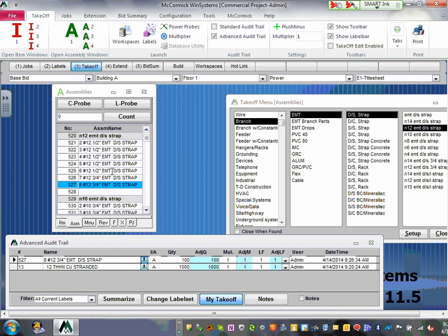Okay, now I know you're not electricians, and it will take you a few. If in doubt, how do you put the system together? Let me know. You have square boxes in a commercial building. Most of the time, what we do is we move with square boxes, deep square box. That's the best way to do it. You go deep, 4 11/16 square box.